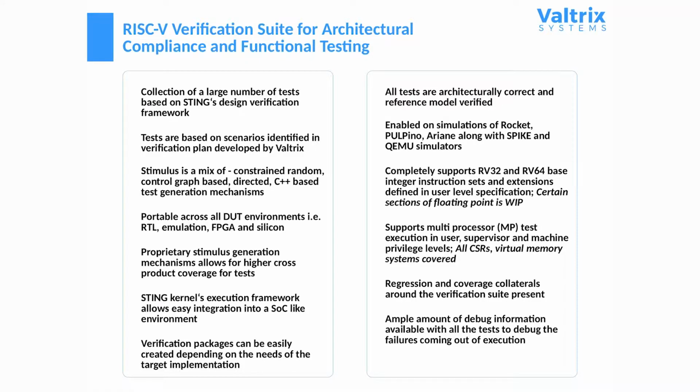We actually run this on Rocket and Pulpino. In the Barcelona conference, we gave a small talk on how we used it on the Pulpino platform. We found about 30 bugs overall on the Pulpino platform, and about 5 of them were quite critical. We found a bug in the multiply unit, which was a fairly critical bug, and which caused the designers to change the design.